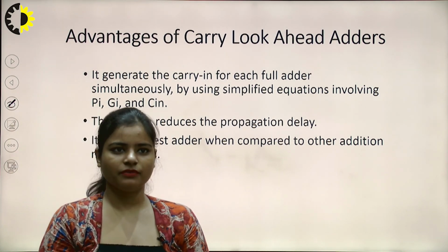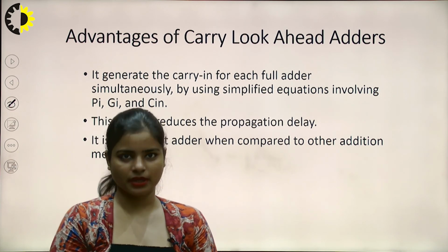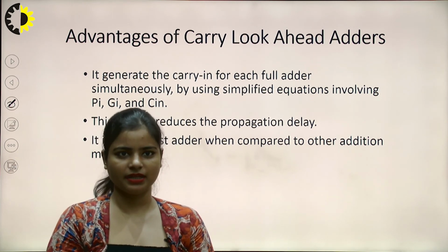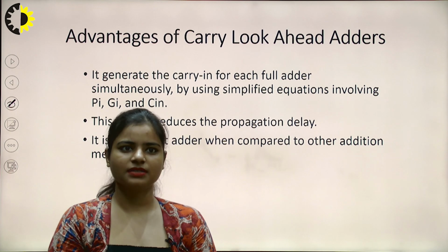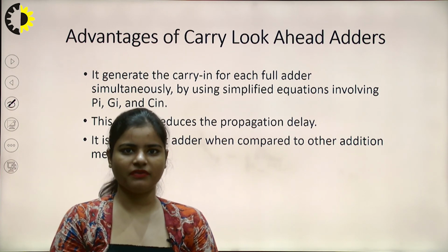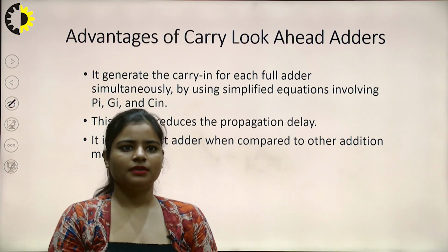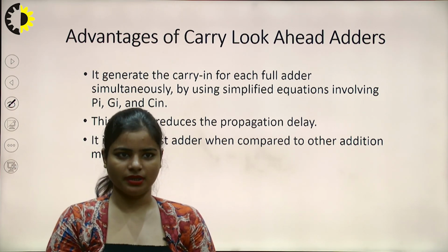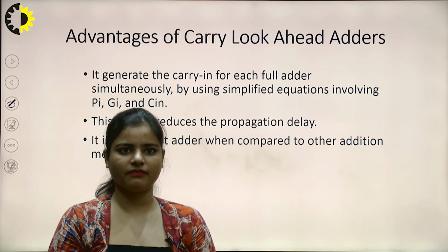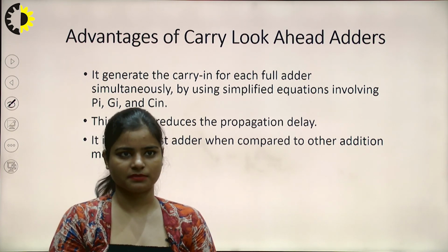Now we have to understand the advantages of carry look ahead adders. It generates the carry in for each full adder simultaneously by using simplified equations involving Pi, Gi and Ci. The system reduces the propagation delay. It is a faster adder when compared to other addition mechanisms.